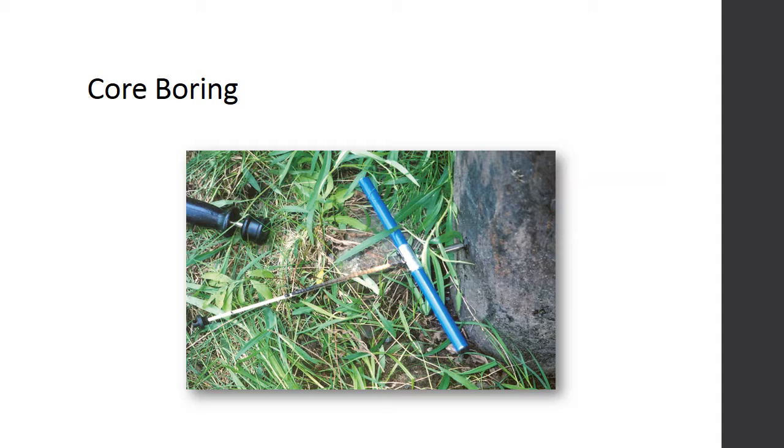Increment cores can be visually examined for signs of deterioration and may be submitted to a laboratory for biological and/or chemical analysis. This method is used far less frequently than in the past, since it is somewhat destructive in nature and because the technology of drill resistance devices has greatly improved, providing a reliable, non-destructive method of obtaining the same information as with core boring.